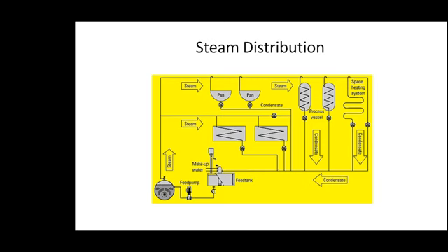And second thing is it also contains heat. The condensate will be at 90 degrees. So when you take it back to the boiler, the amount of fuel consumption in the boiler will be reduced because already we are providing the boiler with hot water. So condensate recovery is one of the most important techniques in the industry. Though of course a lot of awareness has come about, still there is a lot of scope for recovering the condensate. Many of the industries still are not aware of the benefits of maximizing the condensate recovery.